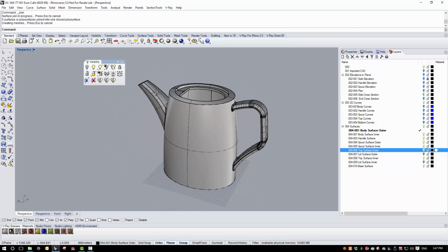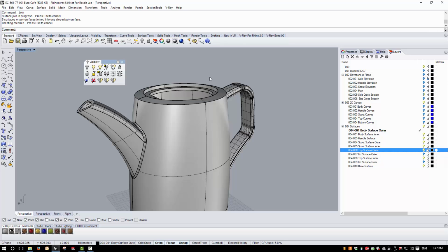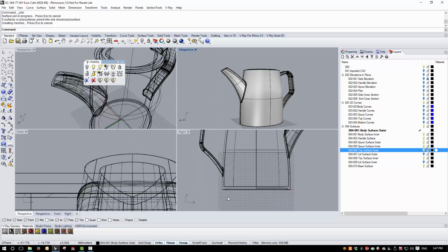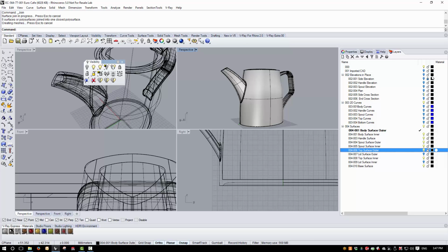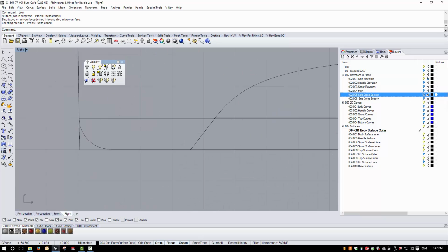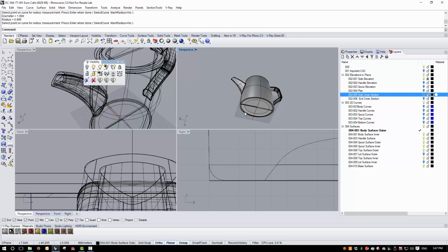and we need to add some minor blends to these sharp surfaces, and again we can just check these off the plans and elevations here. So I'll turn on elevations in place and side elevation, turn off the side cross section, and see if we can get a measurement from this radius here. So again it varies, but it's approximating 1 millimeter.